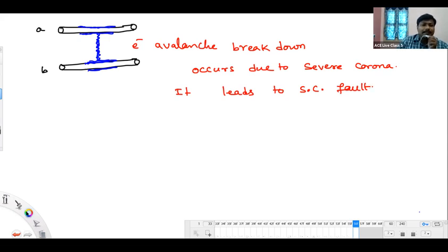Okay, so I think all of you are getting this. So three disadvantages I said. One is the extra energy loss it is creating. Next disadvantage is the radio interference on the communication system. Next disadvantage is the electron avalanche breakdown because of the corona.